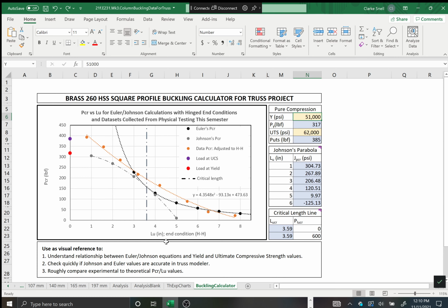And the other thing to think about, what it really comes down to in the real world, is slenderness ratio, which is in the equation. And slenderness ratio is the effective length, K_e times L_u, over the radius of gyration, which is the square root of I over A. So the bottom of the slenderness ratio equation is how effectively you're using the area to resist buckling. Because square root of I over A, if you just think it through. And the top is the length of the member that's exposed to buckling. That's the slenderness ratio. And that's really what you're considering in the Johnson's equation.